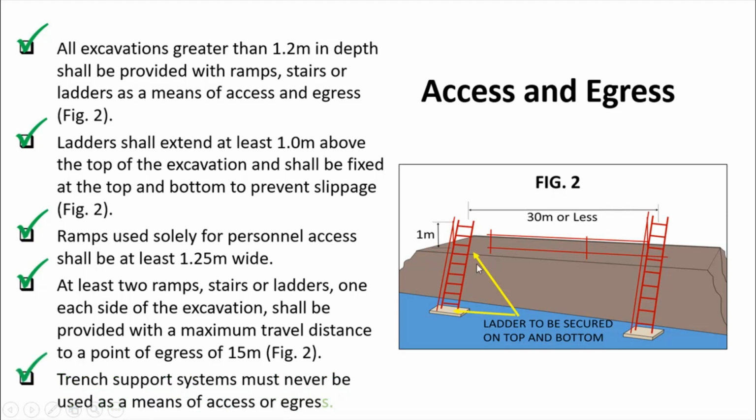Trench support systems must never be used as a means of access or egress. The trench support is only to support the horizontal load. So if you are stepping on the trench support, it will be damaged and you will fall down into the excavation.